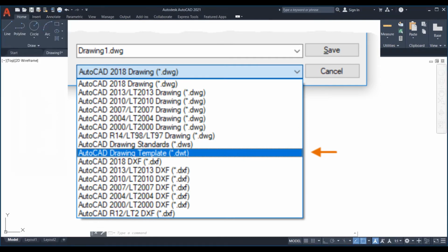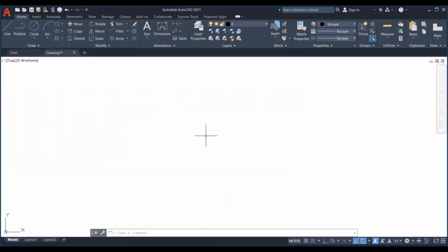Create your own drawing template file. You can save any drawing .dwg file as a drawing template .dwt file. To create a new drawing template file based on an existing one, open the existing drawing template file, modify it, and then save it again with a different file name. If you work independently, you can develop your drawing template files to suit your working preferences, adding settings for additional features as you become familiar with them.